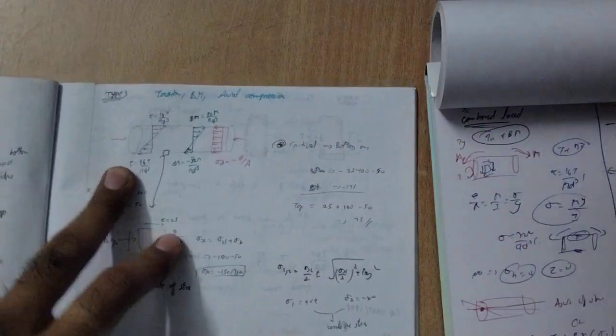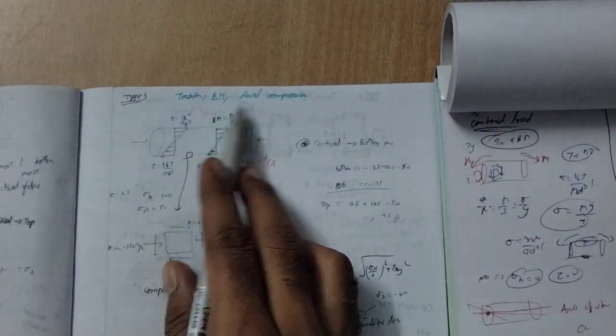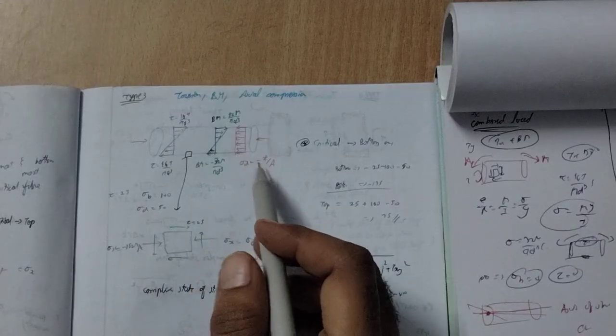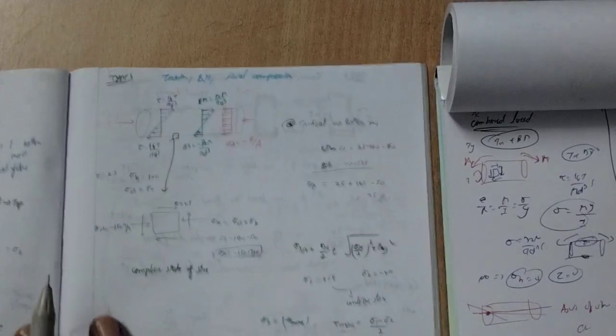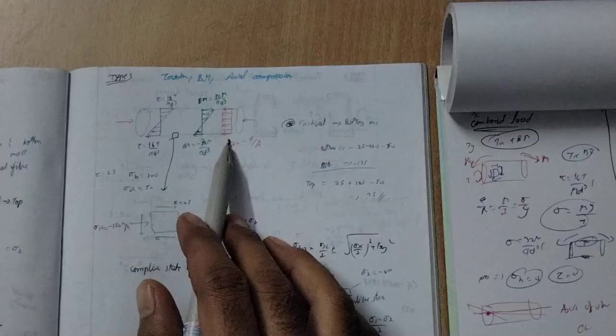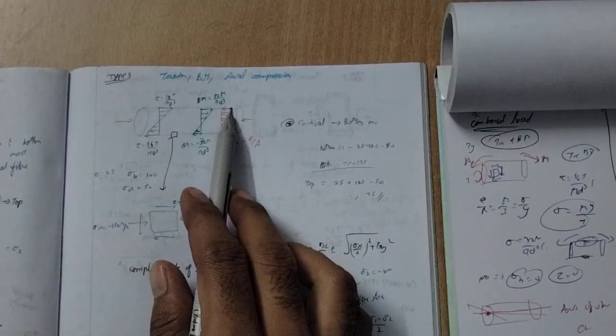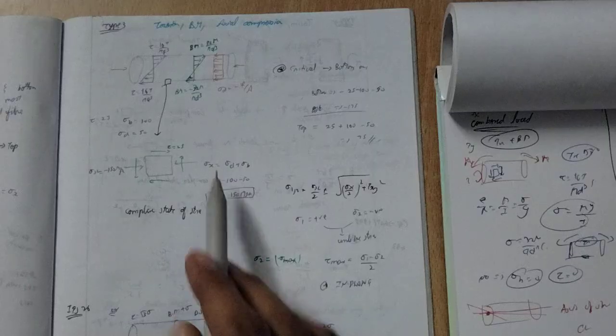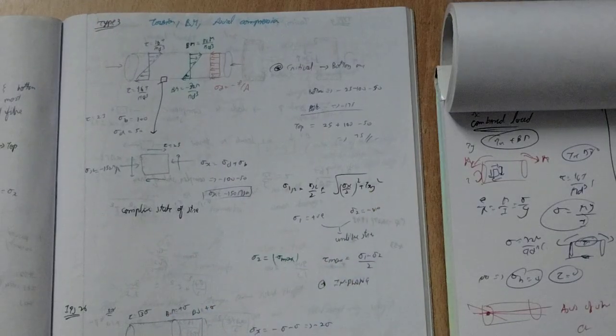so now type 3. Okay, you can see torsion, bending moment, and axial compression. So now it's been compressed in a different way. Okay, now you can see minus P by A. Okay, so at the bottom you can see everything is done, but at the top you can see bending stress minus direct stress is there. Okay, so take the same, it means top and bottom, you just calculate everything and you will get the value. Okay,